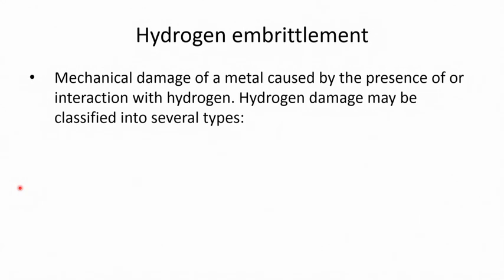You will find that hydrogen is a very dangerous species because it can cause failure, typically by reacting with the surface and forming hydrides. Those hydrides are not good because they are very brittle in nature. In some metals, hydrogen species can diffuse in as atoms, and they change from atomic hydrogen to molecular hydrogen deep inside the metal,